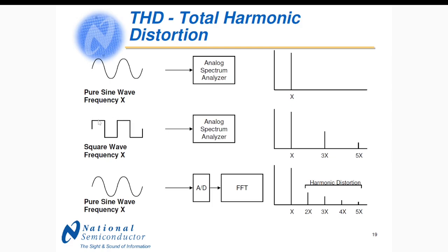But these edges contain every other harmonic, though the significant ones you see are the odd harmonics, like three times the frequency, and as you can see, the amplitude in the frequency domain will be way lesser compared to the primary frequency in the square wave.